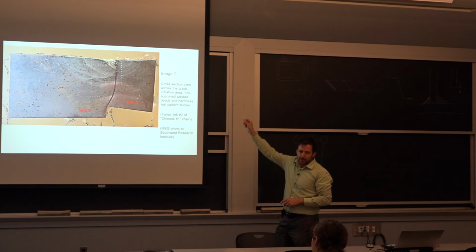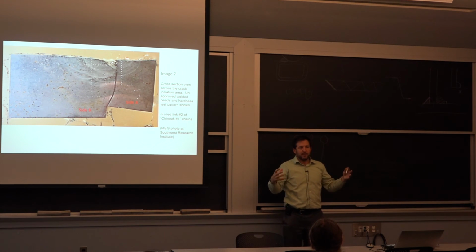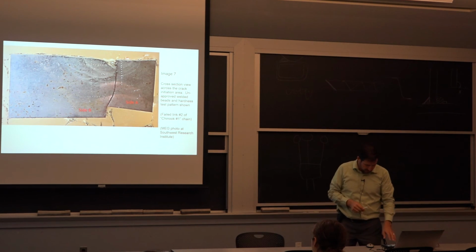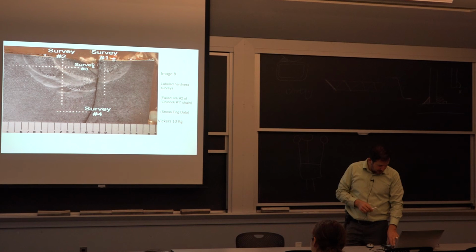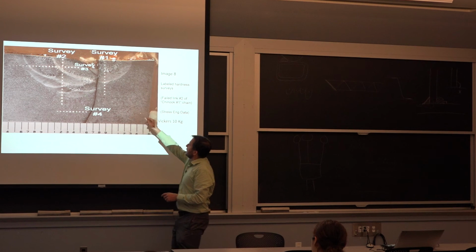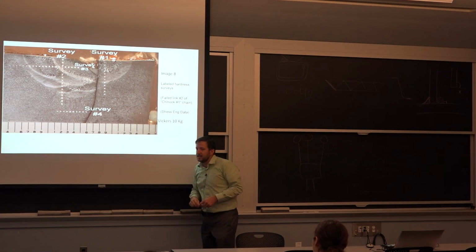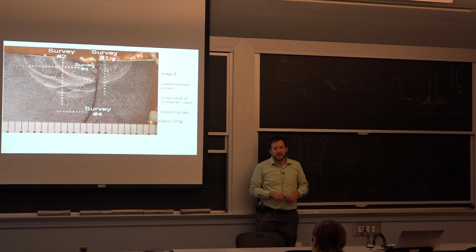So you see these circles, right? These are the heat affected zone. So what happened is they were doing the big flash weld. It didn't work correctly. And then they went back to do some manual welding to repair it. And it failed at the manual welds. So we did some hardness testing through this and essentially found that the hardness in these repair welds exceeded that 35 Rockwell C I mentioned for stress cracking, environmental cracking.